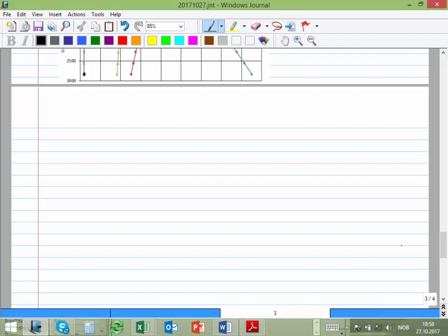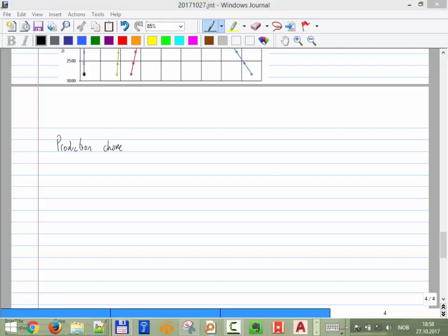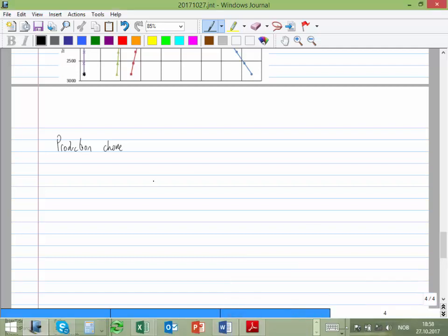So some discussion, like I told you, I'm going to use the example of gas to teach some concepts, but really the choke usually is operating with multi-phase flow. So let's talk about the production choke. Remember we had basically two types. One of them is also referred to as positive, or beam choke, and another type which was adjustable.